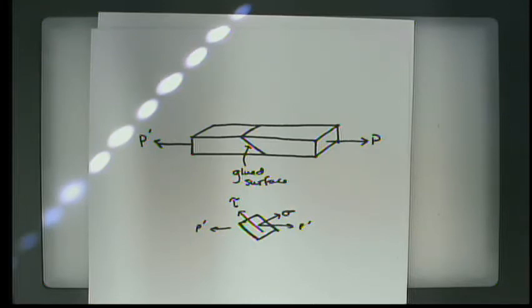And the other reason is that normal stress and shearing stress, when we look at them this way, are perpendicular to each other. So in the same way that we use X, Y, and Z coordinates because they're perpendicular to each other, or radial and tangential components, or normal and tangential components, we're always keeping that orthogonal relationship, because in 2 dimensions it completely describes the state of stress.